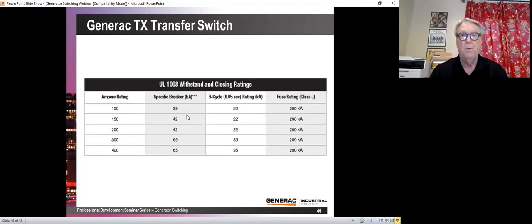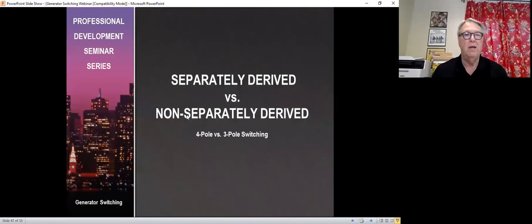And you're going to say, why did you sell me an 800 amp switch? I only wanted a 100. Well, because we needed that 65 kA rating. The other way of doing it is to sell you a circuit breaker based, generally service entrance switch. And that's fine. And I have no problem doing that if that's what you really need is a 65 kA rating. Now, the last thing we're going to talk about is separately derived versus non-separately derived.